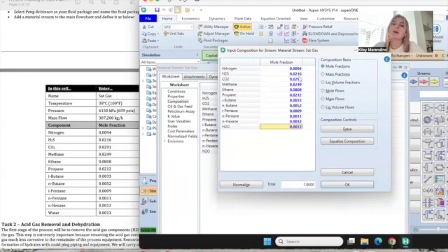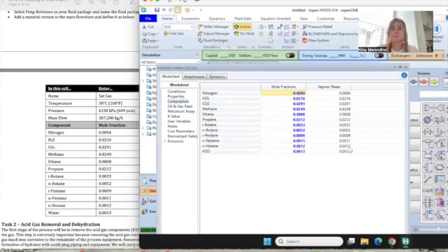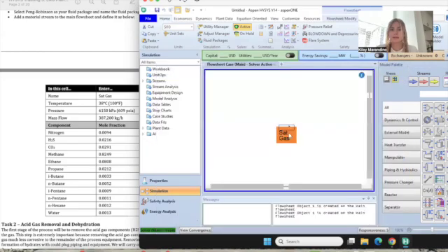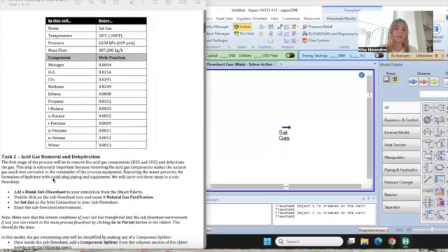So you can see at the bottom, this total is going to be the addition of all of our mole fractions. And whenever you have mole or mass fractions, it should be equal to 1. And if it's less than or bigger than 1, then you know you have an issue and you'll have to go back and edit this. So we're going to hit OK. We can X out of this, and our sat gas stream is now defined.